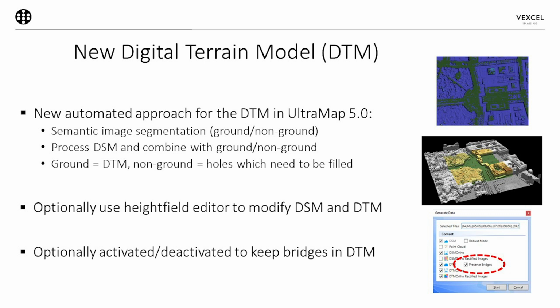The resulting DTM can be inspected for quality control, and in cases where needed, manual editing with the enhanced height field editor can be done. The editor is based on the old DSM editor and was extended with new tools for the DTM, including refinements also for the handling of the DSM, such as displaying and manually setting the value for the height brush.